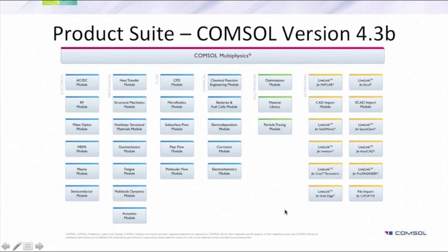Another question we have is, in a model containing primary, secondary, and tertiary creep, can you display the different creep strains? Sure. You can separate the contributions of different creep models from each other. I think we also have models in our model library that demonstrate how this is done.